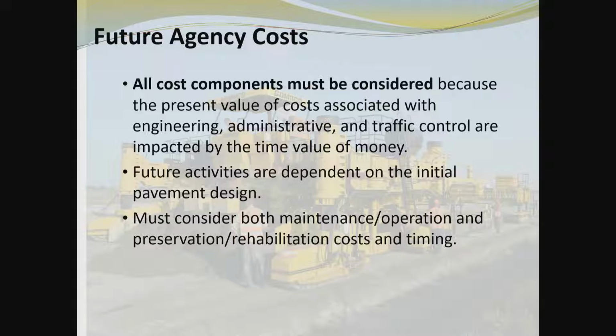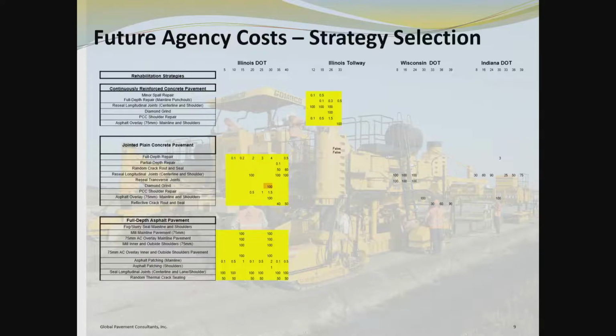You can do preventive maintenance activities. Rather than allow the pavement to ever get down to the level that you have to do heavy-duty maintenance and rehabilitation, you can come in and intervene. So I have a pavement that has some premature joint deterioration. So I do partial depth repairs or shallow depth repairs only at those locations, and it will greatly improve the longevity of the pavement. So in the program, this is another excerpt.